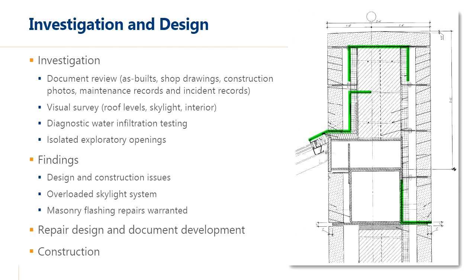because I think the construction photos with the exposed flashings do better justice to kind of show what issues were present. So moving into our investigation, we conducted document review, visual surveys, purposely performed diagnostic water infiltration testing, which is where you spray water on the building and try to recreate the leak. And then with those findings, created some exploratory openings of actually removing the stone and seeing the conditions below to confirm what our tests are seeing.